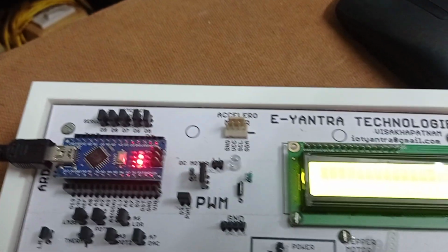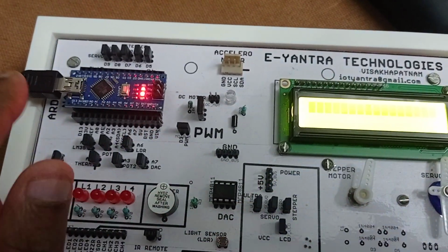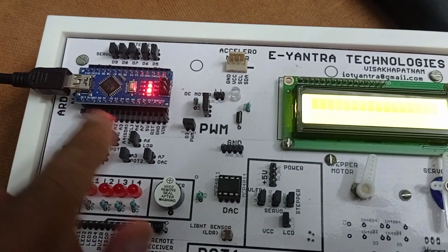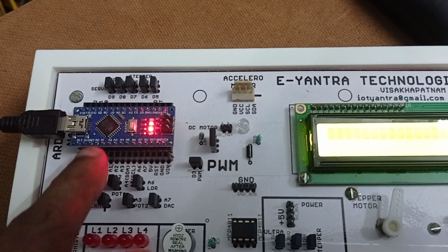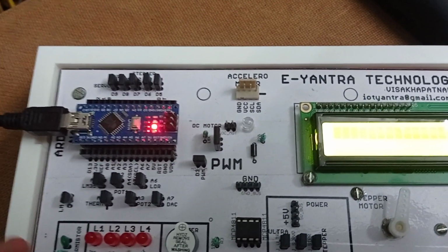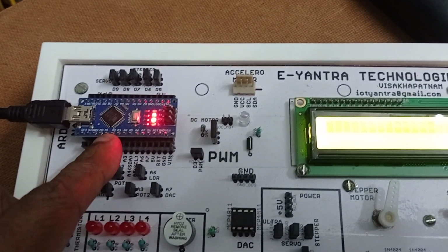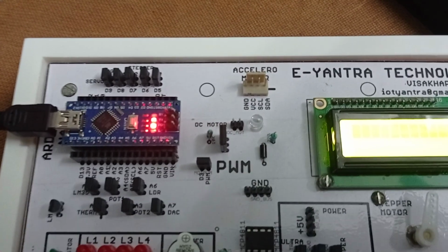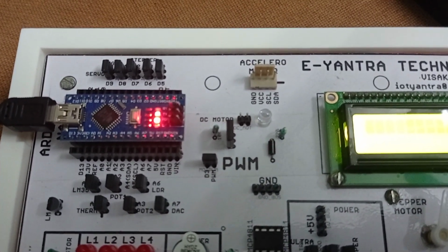As it is a 200 to 300 milliamp drawing motor, we power the motor from USB power only. Arduino is not powering it, because the Arduino pin is not capable of delivering the so-called 200 to 300 milliamp current. So what we do is we use Darlington buffers, and four such Darlington buffers are required. That's why we are using an IC module which is the ULN2003.